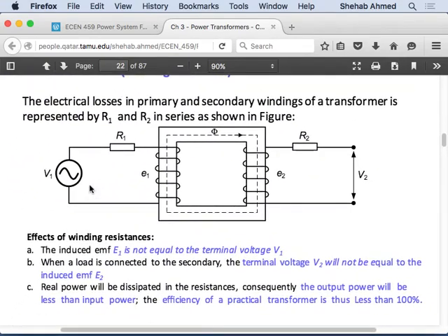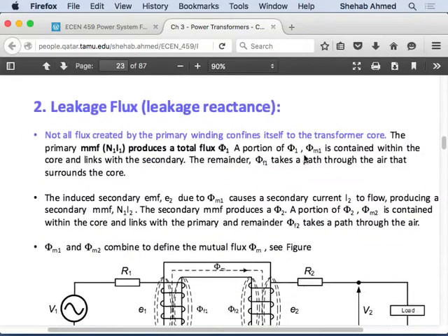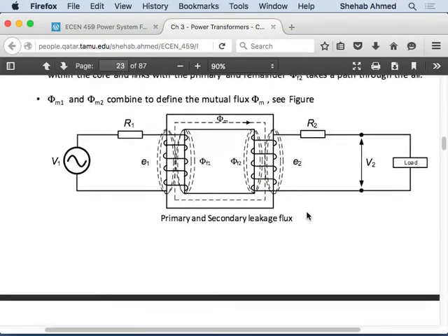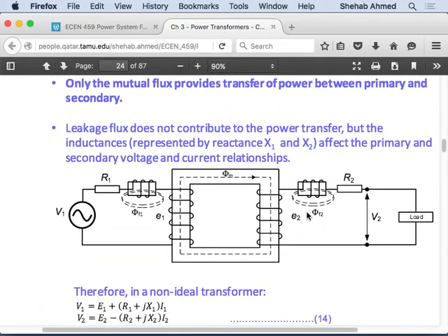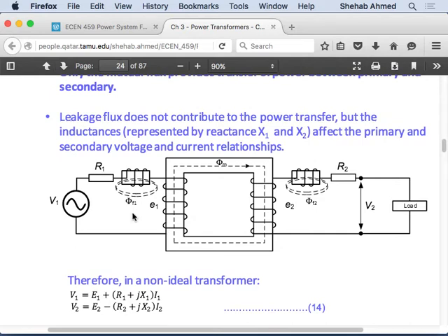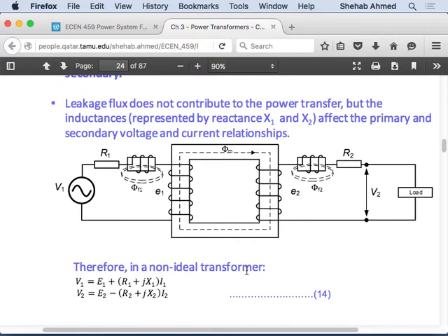Anyway, let's go through the slide. I have one slide on that. So here we added the resistance of the core, the windings. That's taken care of. And then here we looked at the leakage flux that we were talking about, and we said that it has to be represented as a series impedance, series inductance as well, in the path of the voltage. And then you can apply Ohm's law here. Kirchhoff voltage law around the loop will apply. So E and V are no longer the same. There will be a voltage drop between them, right? So I hope that's okay.